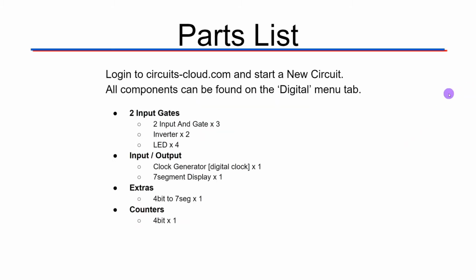The parts list involves most of the general pieces that we have in the Multisim screenshot, which we'll look at in a second, with the major exception of the AND gates. This is a modification of the actual circuit logic that we need to enable the reset, which in turn provides the Modulus 10 behavior, counting from 0 to 9 as a range, specifically because we do not have a 4-input NAND gate.